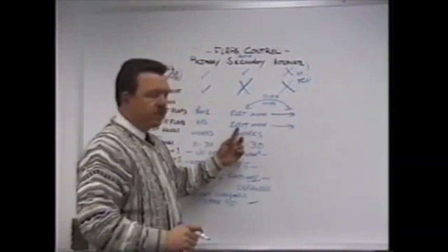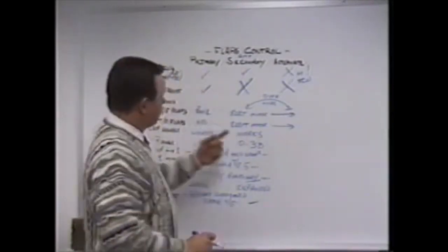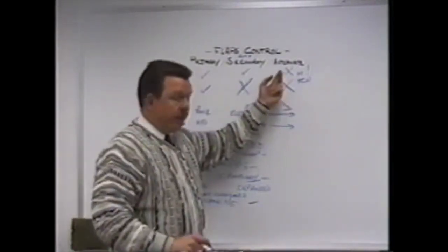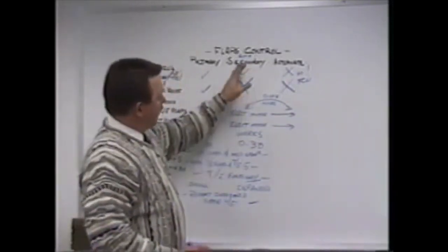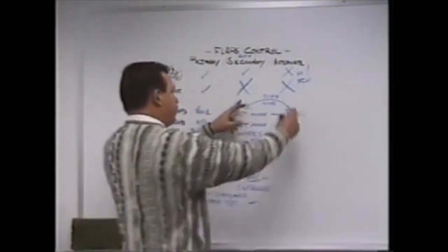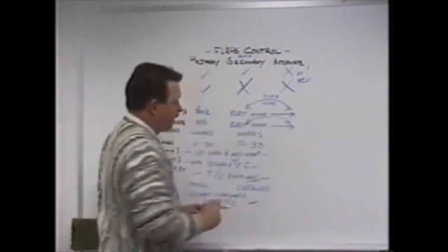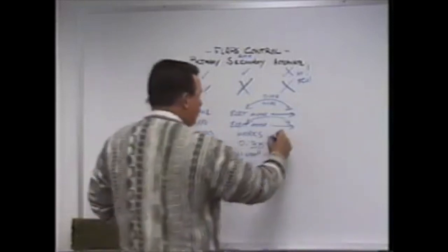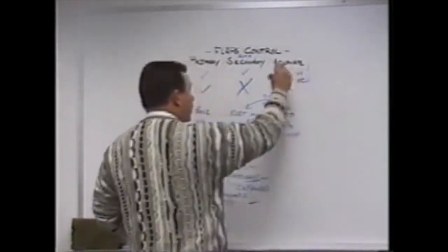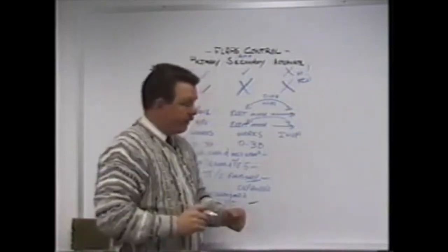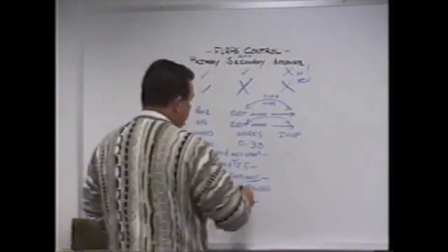So if your electric motor is giving you problems, you're not going to be able to deploy the affected flaps in either the secondary or alternate mode, but then the primary should have driven it out fine. If it's a control mechanism, then the electric motor should work, because we're going to use different wiring in either case. It's going to be different wiring with the same motor. The flap panel does not work in the alternate mode. So if I arm that alternate flap arming switch, the flap panel is dead. You can move it all around, nothing's going to happen.